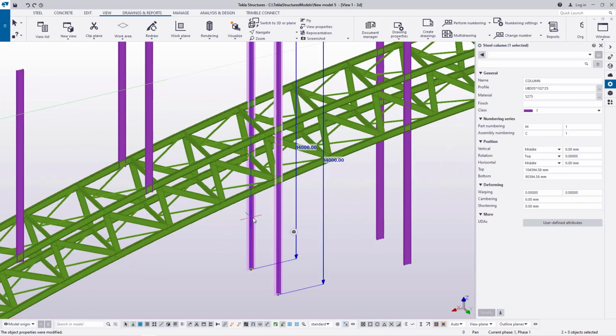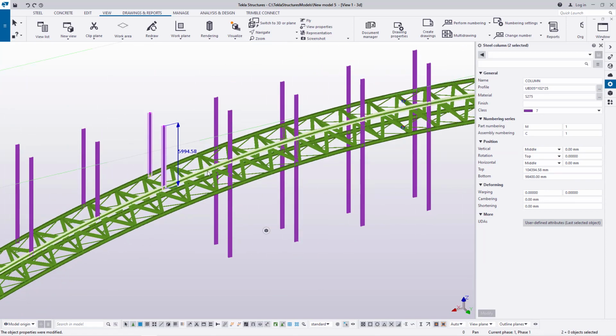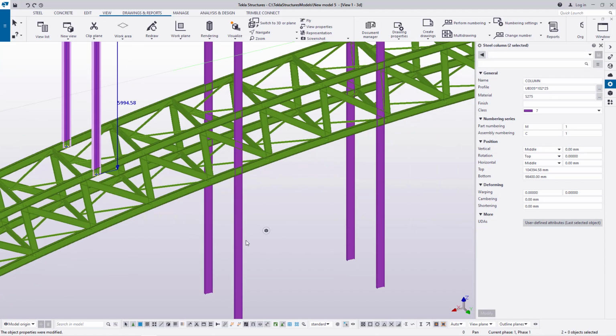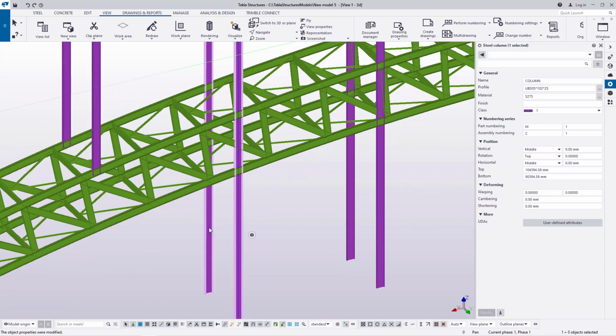Select on that and double click on the other one, and we change this one to 98,400. 98,400 will work much better for us. We'll go ahead and click modify, and that's how we trim them. You just change the level. Select on that, double click on that, and we'll change this to 98,580. Perfect. And that is how it changes.